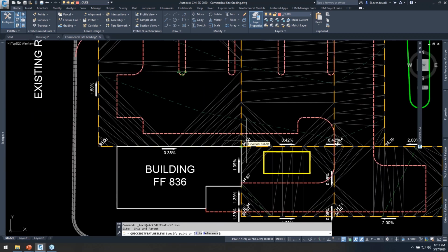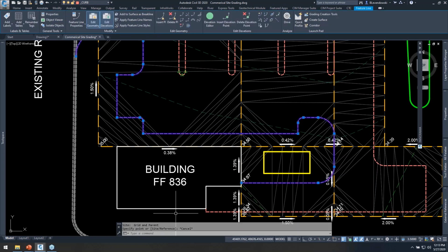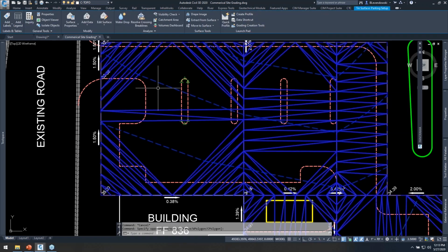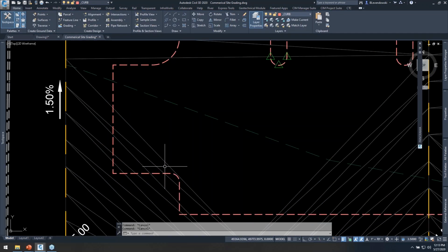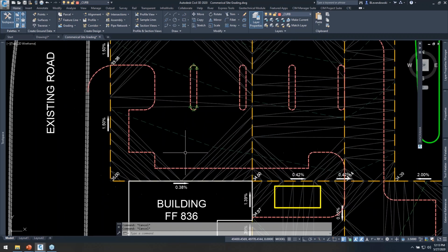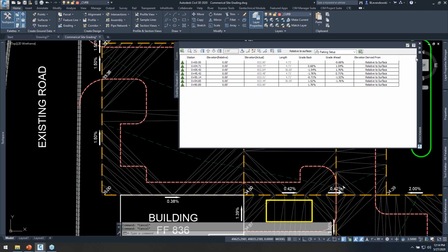And if we want these feature lines to stick to the parking surface, that's what we'd want to do, okay? That's the workflow I'm showing here. What's the alternative? Don't make this relative to the surface, and don't put these in the same site. Take your elevations from your setup surface one time as kind of a starting point, and then if you do more independent grading of those feature lines, run with that. So two different ways to handle it, but I'm going to show you how to do it kind of the most dynamic way. Oftentimes, though, the more dynamic it is, the less flexible it can be.